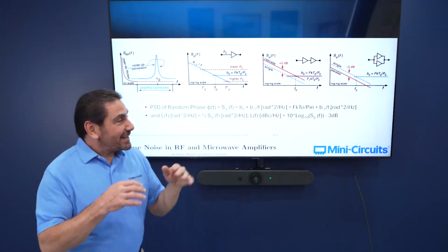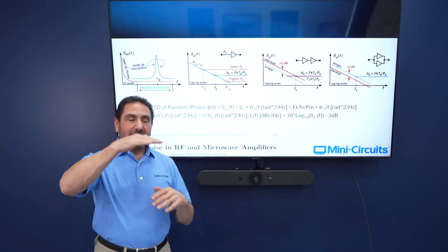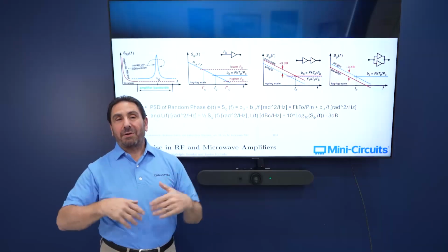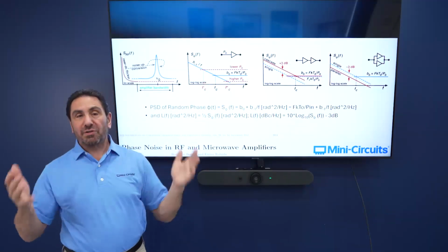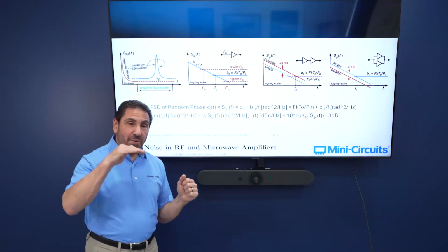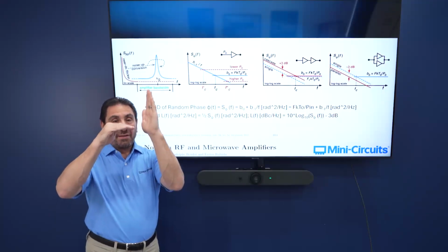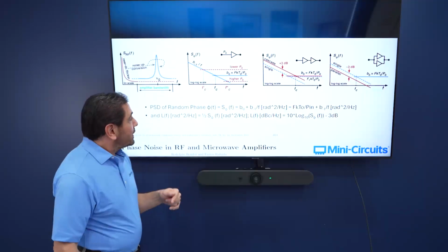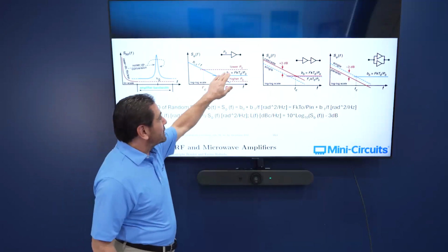Not really. Don't forget, this is a dBc measurement. So assume you have noise power, it doesn't change. As you increase your signal power, your signal-to-noise ratio is going to improve. So that's what's being illustrated here, that as you increase the signal power, the signal-to-noise ratio improves, assuming, big assumption at some point, that the noise power is not changing. Because once the noise power starts to increase, then your signal-to-noise ratio may actually stop increasing, and as we'll see, it might actually invert. So two common or logical things to ask are, well, how low is low and how high is high?